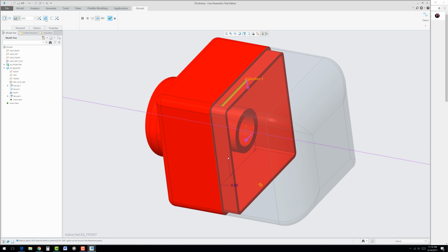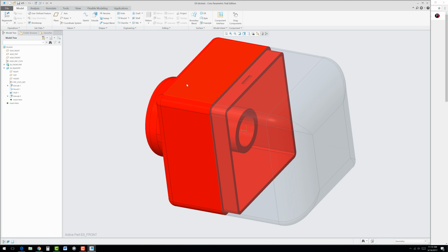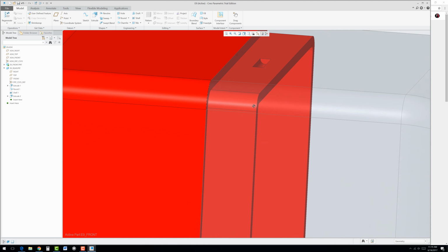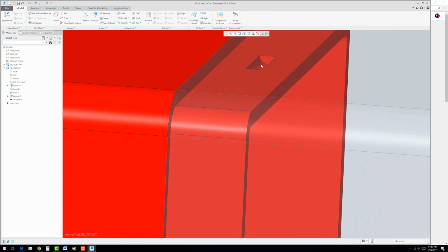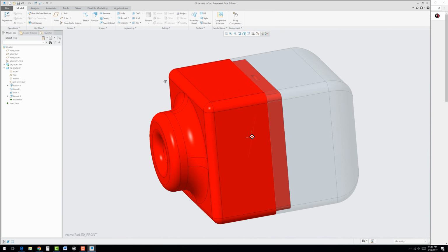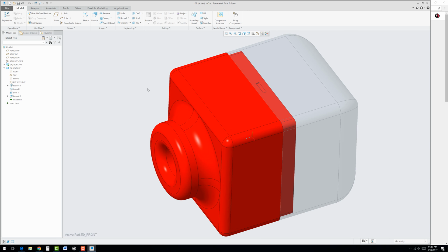We're going to go to remove material. We're going to do mid plane once again and 0.255. Again, just adding a little bit of tolerance in there. Hit enter and the green check mark. And if we zoom up closely, let's see. Kind of hard to see it in there, but now we do have the mechanism for both sides.